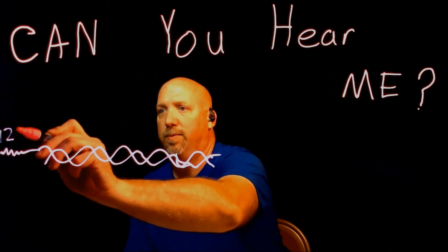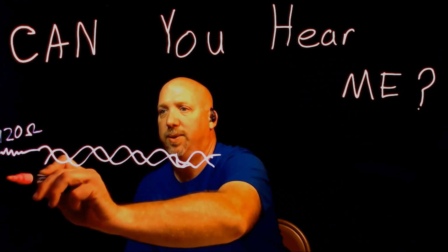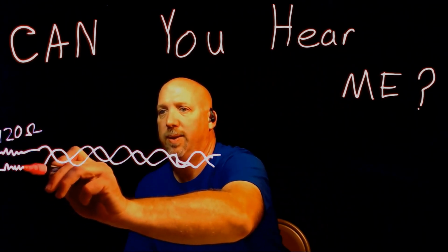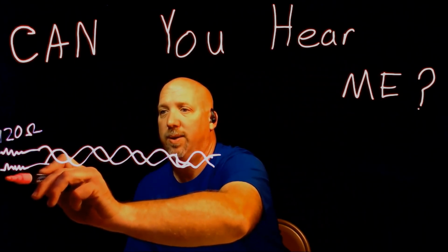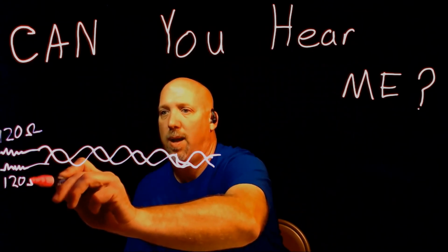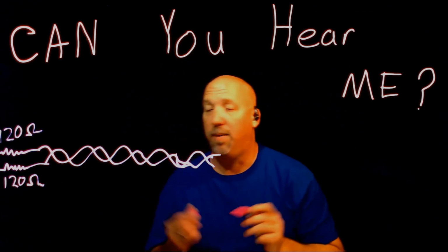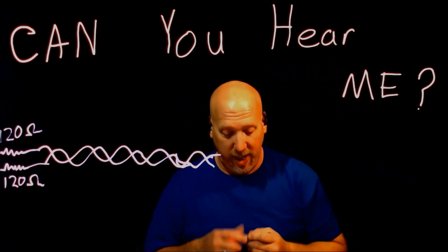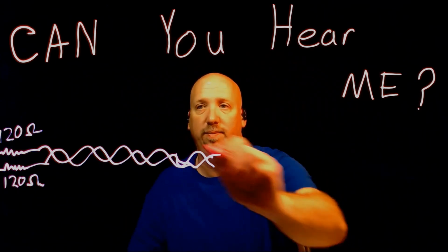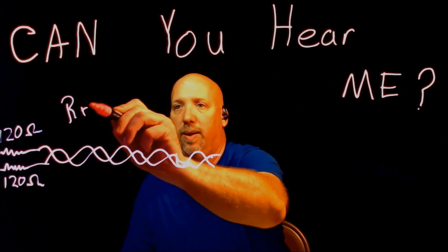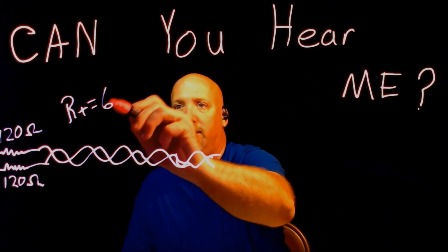there's a 120 ohm resistor. And at the other end, there's a 120 ohm resistor. Now, those 120 ohm resistors equal a total resistance of 60 ohms.